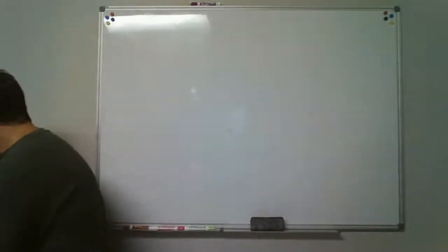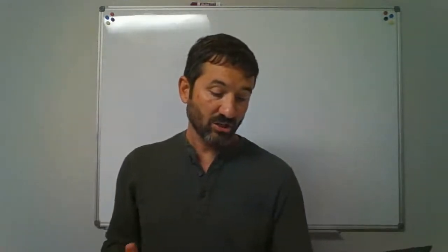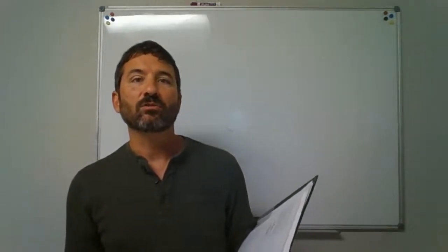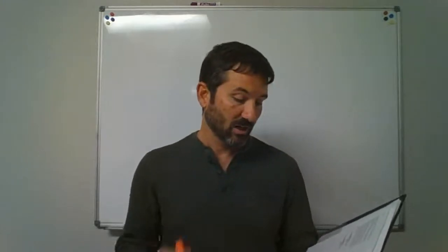Okay. It does have some exceptions. This section shall not apply to fixtures with integral traps. So can you think of a fixture that has an integral trap? First of all, you might be saying integral. What does that mean? Integral, it's built into it. So is there a trap that's already built into the fixture itself? Can you think of one of those? And hopefully probably the one that you're thinking of is maybe the water closet, the toilet, that you've got a built-in trap inside there. Does not apply to that.